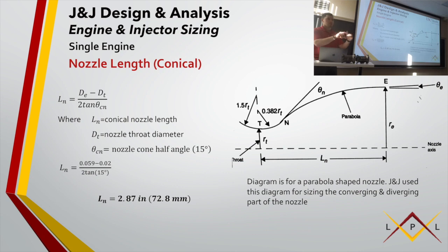The pressure is gonna change quickly, which ends up in losses and things like that. So you might see the converging part doesn't really matter as much as the diverging part, because at the end of the day, going to Mach 1, it ends up just doing it. So it doesn't really matter. It's this flow, because if you want the most efficient nozzle flow kinetic energy out of there, you kind of want that to be the best.